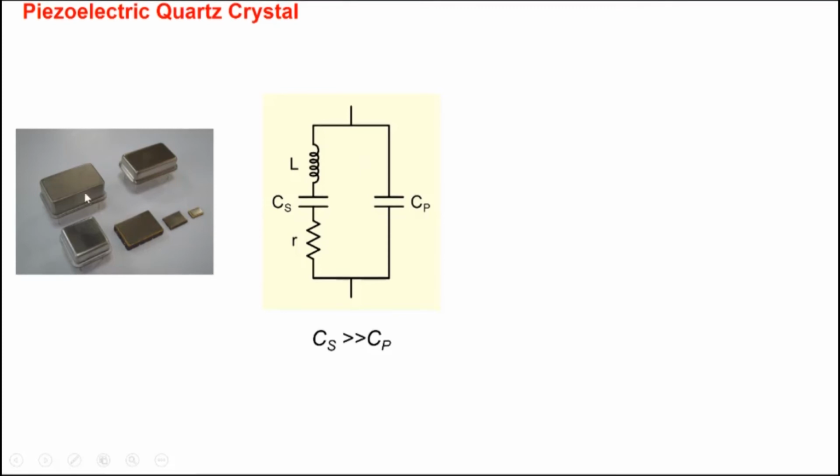So the equivalent circuit of a quartz crystal with electrodes on two sides is a series LCR, with a parallel capacitance also.